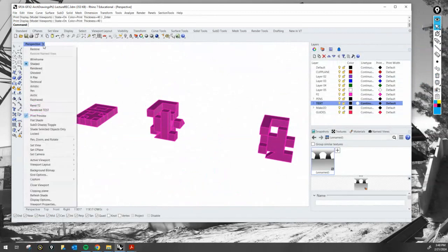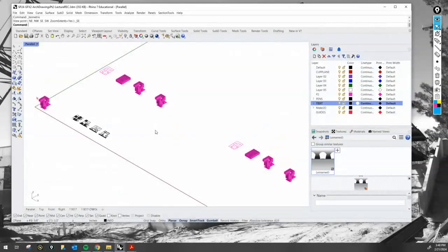Setting it up is simple. I'm going to be working on the southeast, I believe. So Set View, Isometric, Southeast View. Notice how you get a view of your entire screen, and you get that rigid isometric view. You have your axis going this way, and your axis this way.